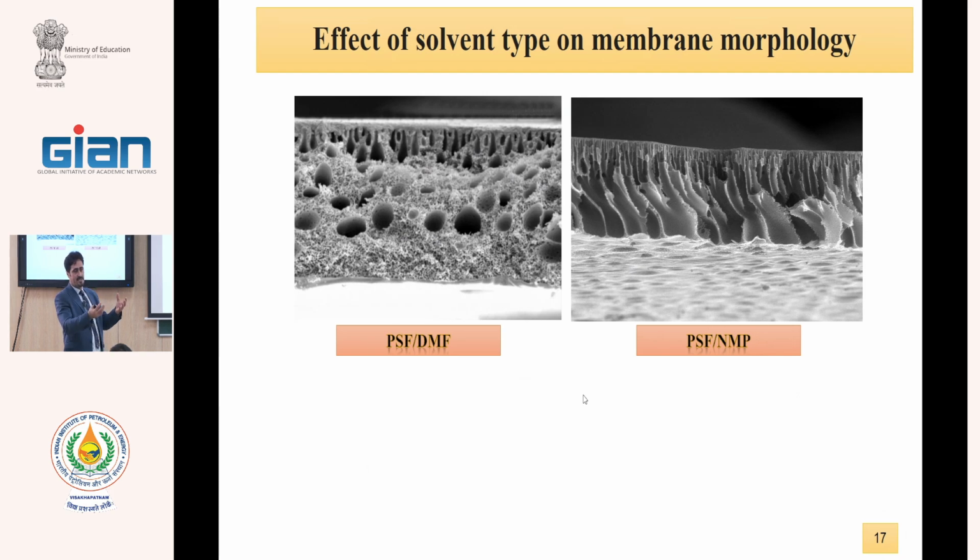Ultrasonic disperses the nanoparticles well, and after good dispersion, we add the polymer and let it dissolve completely. It is the simplest method, but we can also add a coating layer, we can spray the nanoparticles, and use different methods. Thank you. I will discuss tomorrow.